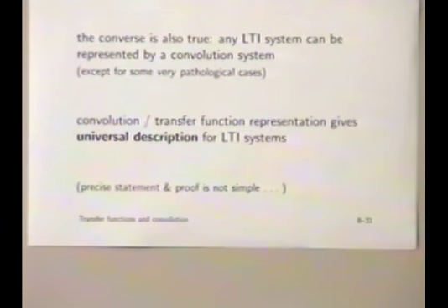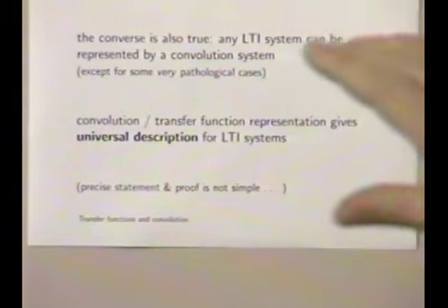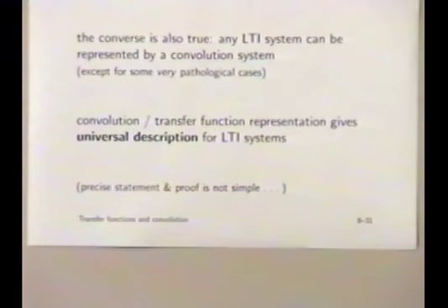And so what that means is that this whole system is in fact linear, and since it's linear time invariant, all you really have to do is measure the impulse response. If you measure the impulse response of that system, you can go back and, with MATLAB or whatever you like, simulate the effect of that system for any other input. For example, your favorite music can be played through it, and you will find out exactly what it would have sounded like at that point. Okay? So this is sort of the idea.